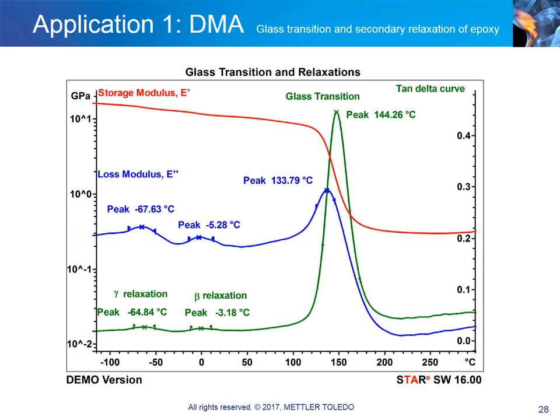The use of a multiple frequency thermal scan means that relaxations can easily be separated from other events, such as melting and water evaporation, since these exhibit no frequency dependence. Secondary relaxations play an important role in the impact resistance of materials.